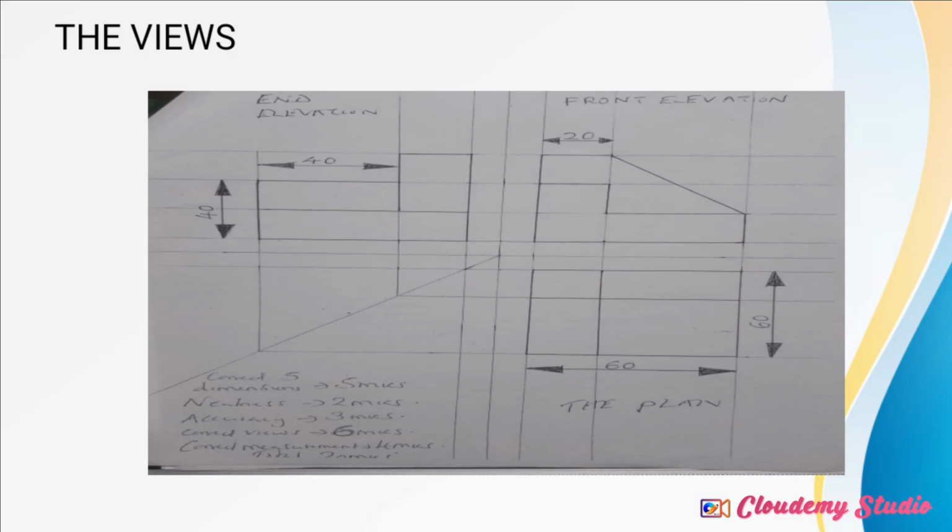And you also have to make sure that all those views are in proportion. There is no one that is overlapping the other. And you look at my dimensioning. I did dimension 5 major dimensions in any of the views, as I followed the rules for dimensioning.